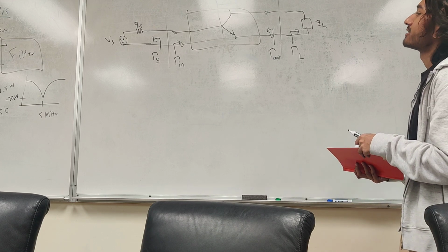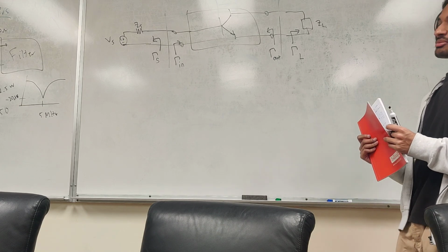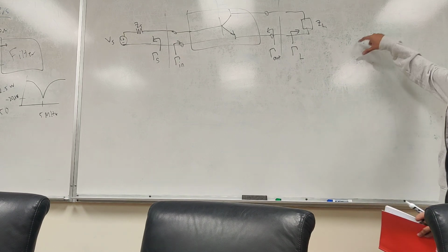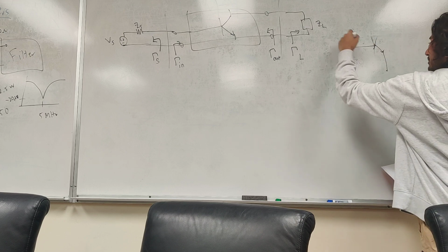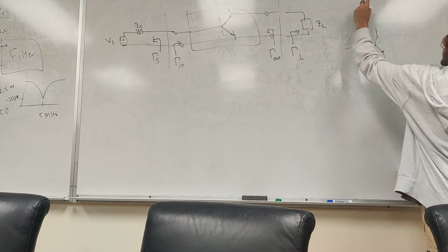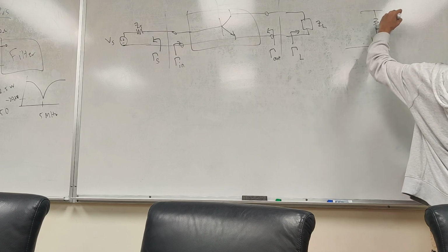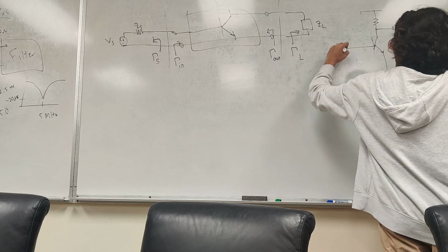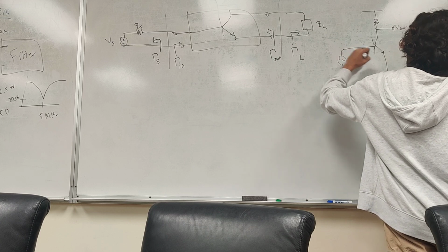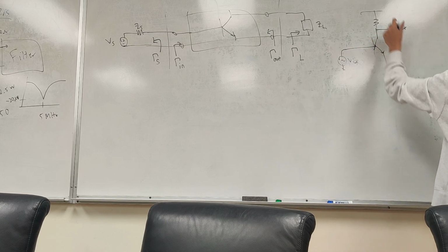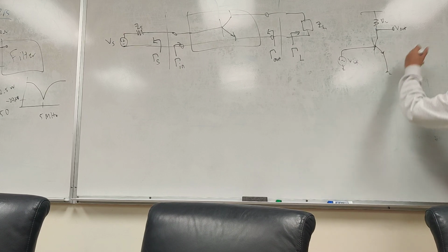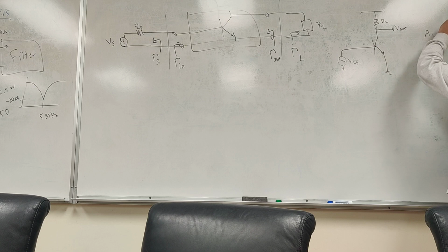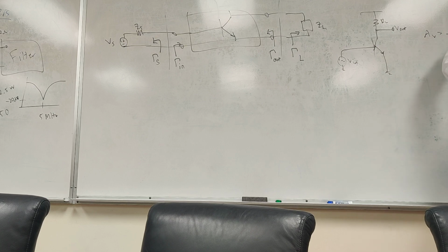This is where it gets a little tricky. Okay. When we made amplifiers before, we had a BJT, I'll draw it out. BJT, I'm going to ignore the biasing network for now. Resistor, this is our V out, this is grounded, goes RC, assuming it's biased forward active region, small enough signal, the gain is negative gm, RC parallel, ro, right?